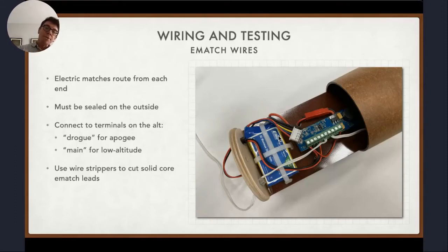And the other thing you'll notice, see how on the plate it's stepped? This actually creates a little bit more tortuous passage for gases to get through. They have to get around the outside of the disc, through the flat part of the step, through the lip. It's never going to be perfect, but the more you can protect the electronics, the longer they'll last.